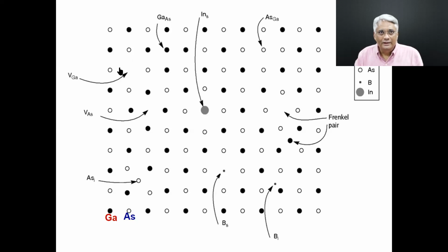So you can basically have a gallium vacancy, a Schottky defect, a vacancy created because you have a missing arsenic atom, and arsenic going to the interstitial site. This is basically a gallium arsenide lattice, gallium arsenide, the well-known semiconductor. And you can also have this missed site occupation. Okay, this can also happen. Gallium at an arsenic site and vice versa is also possible.